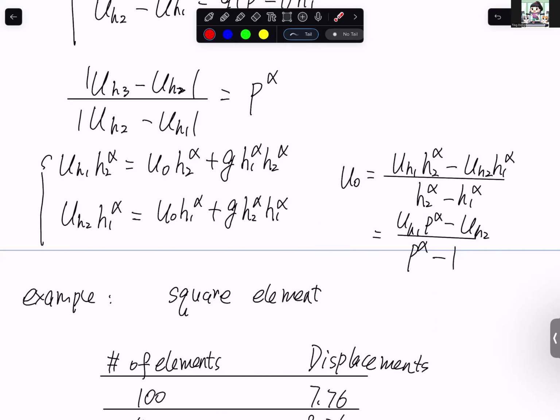In this process, we are losing some flexibility because of the lower order. Losing flexibility means that in K, Q equals F, the Q is lower than the exact solution. When we convert Q to strain, strain is lower than the exact solution. When you convert strain to stress, stress is lower than the exact solution. So in the convergence study, it should always converge from below, which means lower, higher, higher, higher. Great question. Thank you.